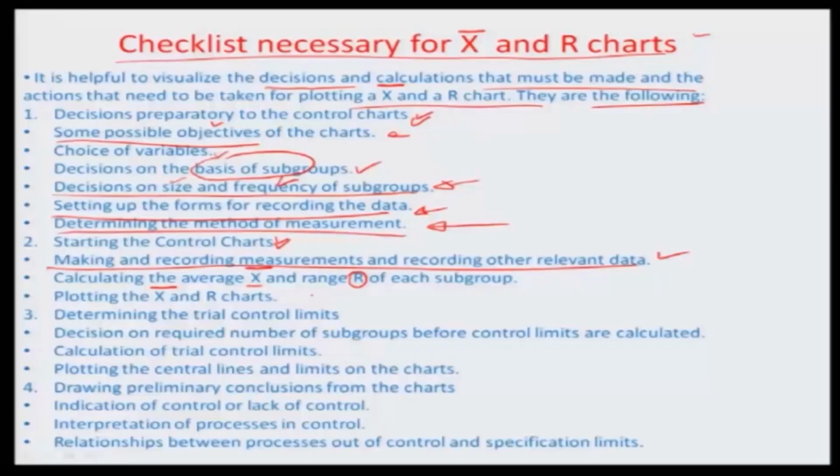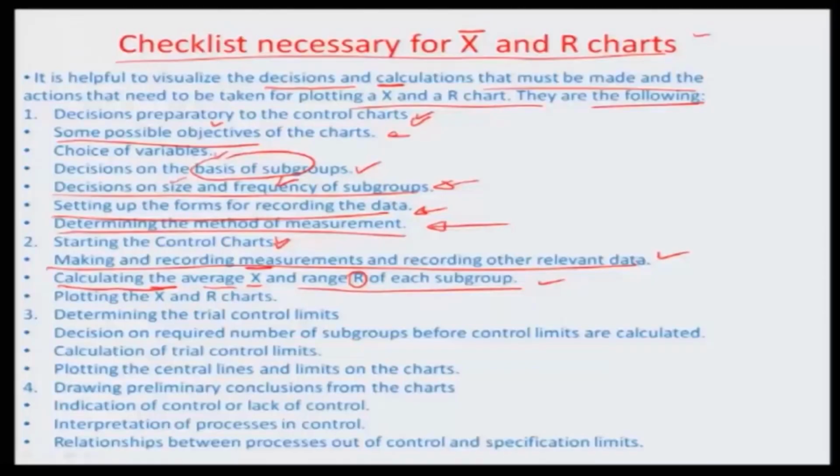So, this is how you make extensive observations in a relevant manner, which you align with your thought process on the observations that you have already made. You probably are aware of the cycles as a supervisor, where there may be a chance of defectives, and so your subgrouping and your interval of grouping will be based on that experiential domain knowledge. So, it becomes a very accurate sample, based on that experience.